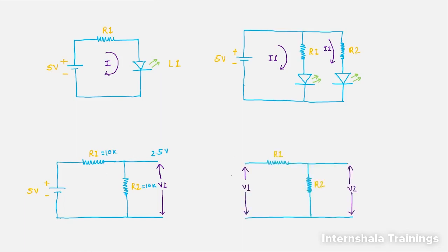Now let's consider one more circuit, which is similar to this one. Let's consider that there is a 5 volt device generating a square wave whose amplitude is 5 volts. So this is 0 volt and this is 5 volts. There is another circuit on the output side, and this circuit works on 3.3 volts. If we provide 5 volts directly to the 3.3 volt circuit, it will get damaged. So with the help of a resistor combination, by dropping the appropriate voltage across the resistors, we can achieve 3.3 volts on the output side.